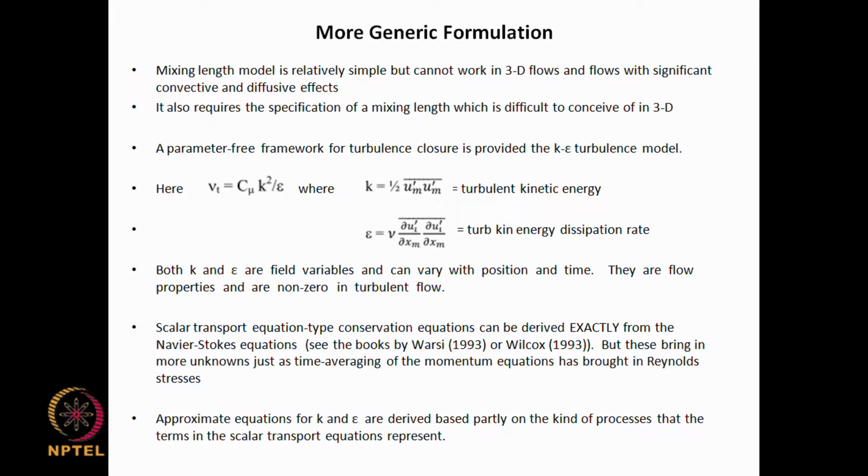These are well known disadvantages of a mixing length model, and people have therefore worked quite a bit to come up with a parameter free framework for turbulence. We do not want to have a parameter called the mixing length which we fit to explain the turbulence.